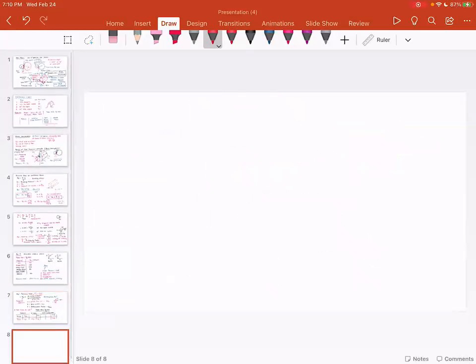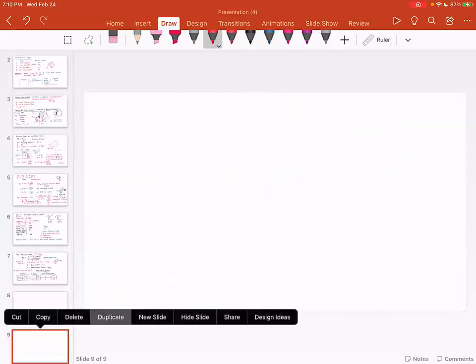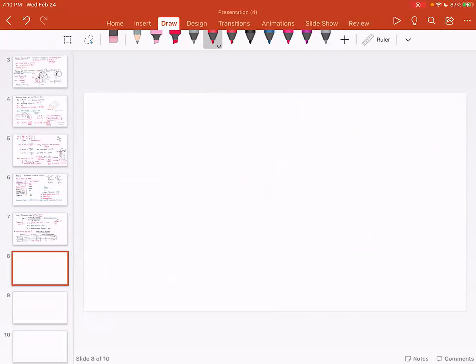Alternatively, you can actually use an equation and find out this value of C, the deformation factor, based on the material of the gear and the material of the pinion. There is no preferred approach. I usually go with the tabular approach, but you are welcome to use this equation approach, which is given as K times E divided by 1 divided by the Young's modulus of pinion plus 1 divided by the Young's modulus of gear.